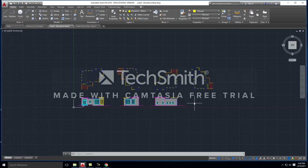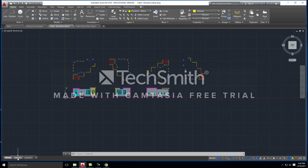As we mentioned when we started AutoCAD, we didn't really ever look at Paperspace, but when you're inside model space, which is going to be the area where you're doing all of your drawing, you're drawing everything at full scale, okay? If a wall is 6 inches thick, you draw the wall at 6 inches thick. If the wall is 20 feet long, you draw the wall at 20 feet long. It's a simpler way of drawing your house, okay? If you actually had to draw things at scale, it would be a nightmare because you'd be converting every single line in your head to a certain scale. Believe it or not, I've seen it happen in the real world. People have drawn things at scale.